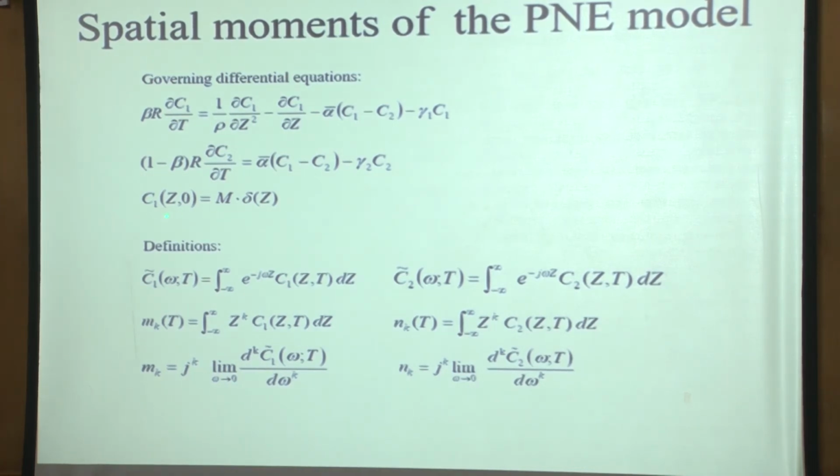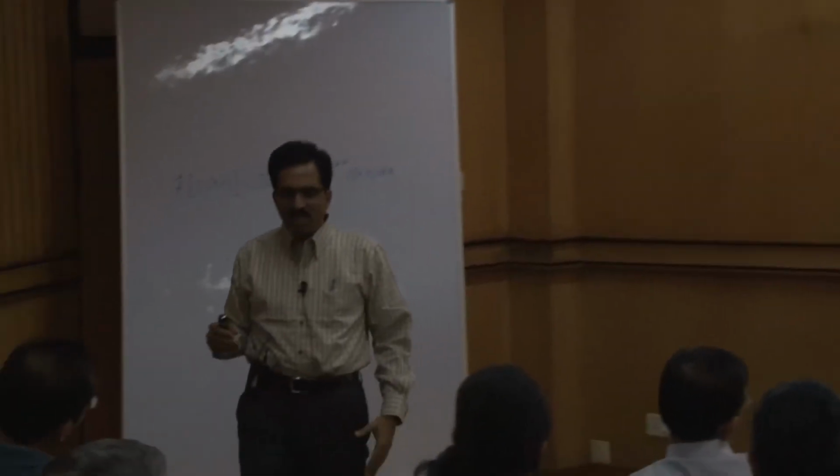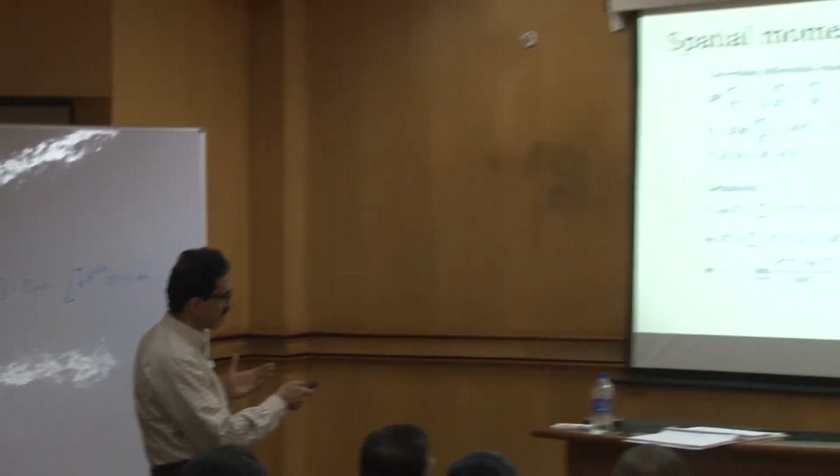So our boundary condition says that it's a one-dimensional problem, and at time t equals 0, all the mass of solute is introduced at z equals 0. With time, it's going to spread in both the positive and negative directions. As I indicated, when this happens, some solute mass escapes into the negative z direction as the plume spreads and moves, but after a while all of it will come back into the positive z direction, because advection will pull it along in that direction, and eventually it will not be spreading far enough to go into the negative direction, right? So it's something that we are aware of.